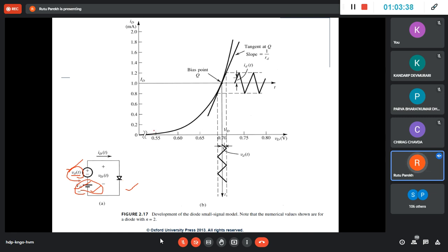So this millivolt falls here somewhere. Here, the diode is always dead. If this voltage is big enough, then you don't need this. If I'm talking of 200 volts, let's say, then 0.7 is nothing, and it is always on. From 200 volts, 0.7 is a little voltage drop, and it is still 199 point something. So it is not necessary to have this bias voltage.